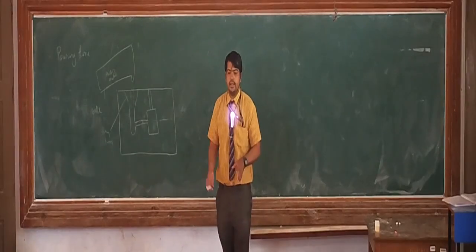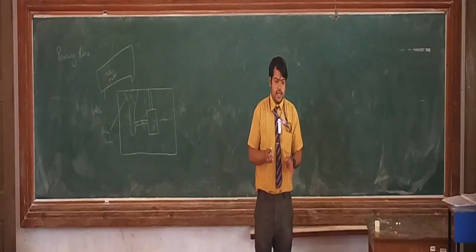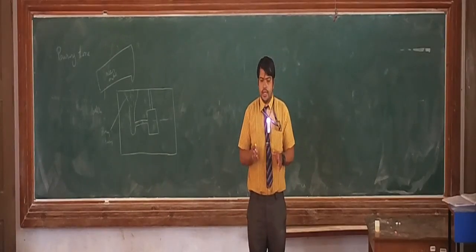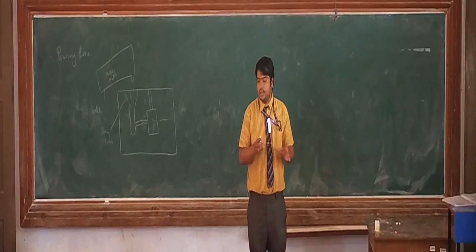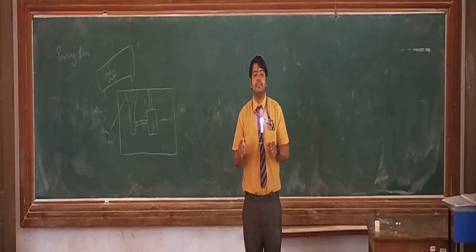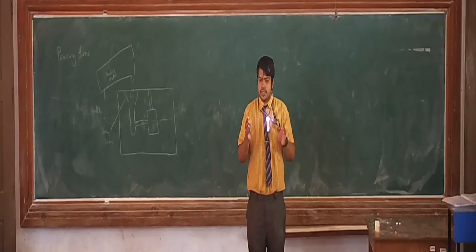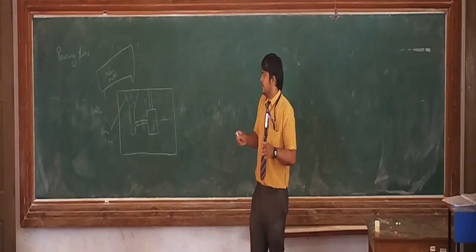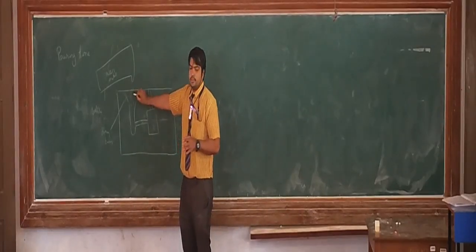As I explained in the earlier classes, we melt the metal in the furnace, and after that we take the molten metal from the furnace with the help of something called a ladle. From the ladle we take this molten metal to the pouring station, where the prepared sand mold will be, that is the assembled cope and drag of the sand mold, and the spout of the ladle is directed towards the pouring basin.